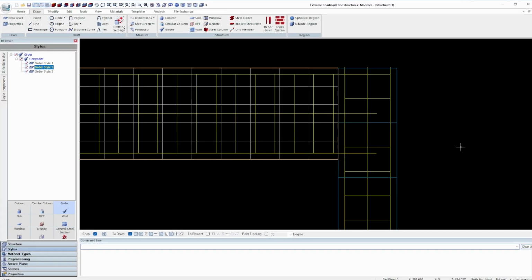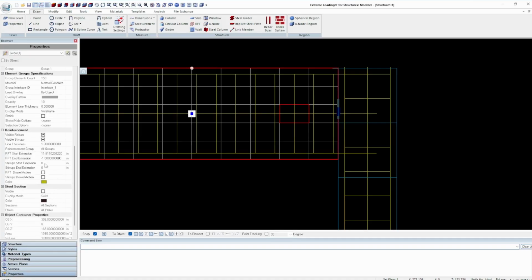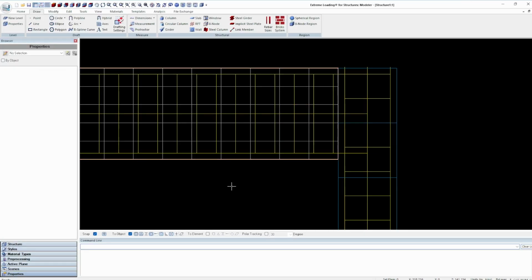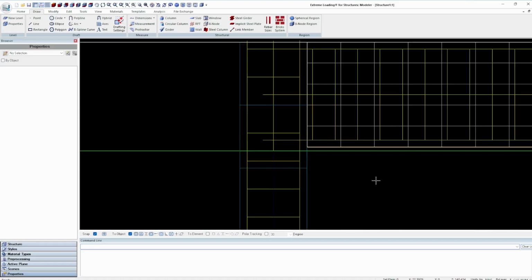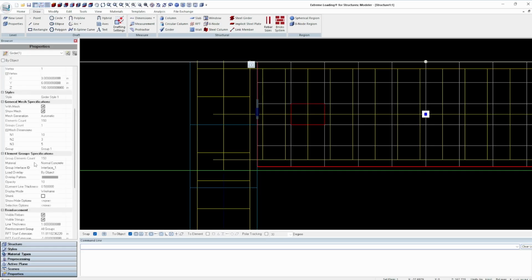In examining the girder reinforcement extension into the column, we can see that the reinforcement is extended past the midpoint of the column. If we allowed this for girders on both sides of the column, the springs generated between the elements at the center would also be duplicated. Hence, we will instead set the extension of the reinforcement bars at the start of the girder to 9 inches only. For the other end span, we'll set the start reinforcement extension to span the whole width of the column, or 18 inches.